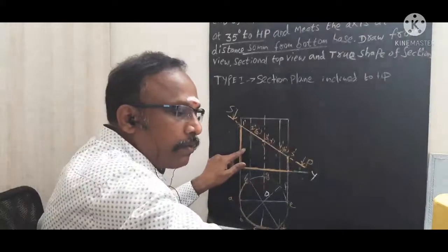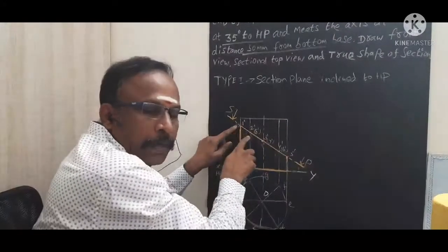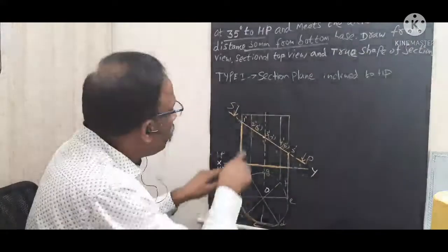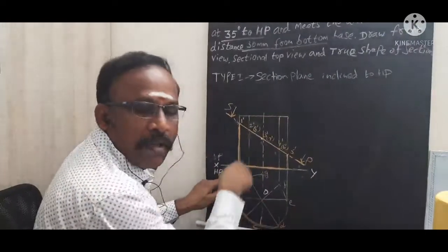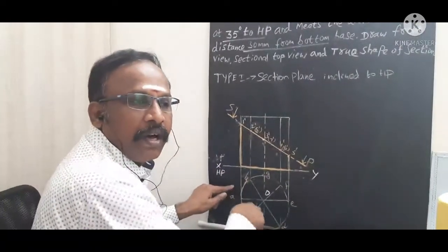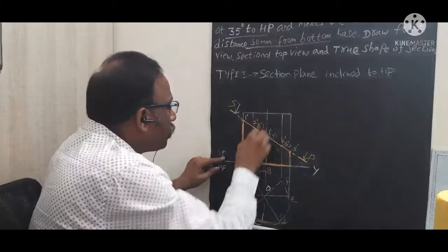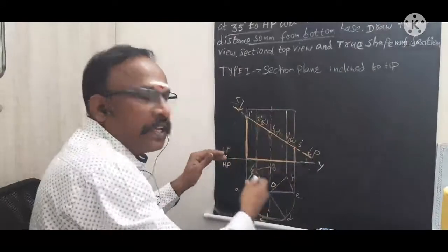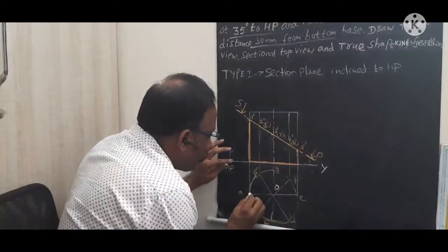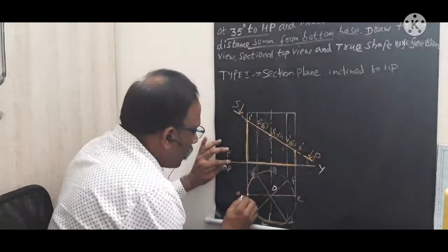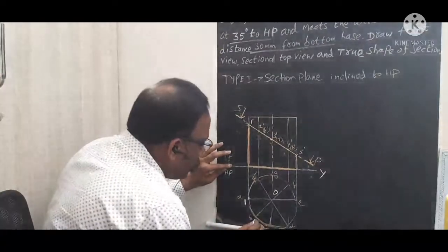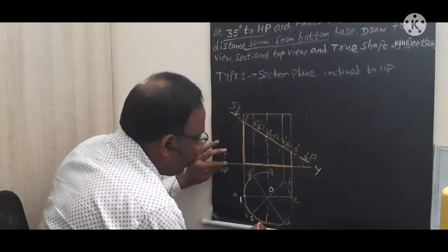Now, next step, we want to project these cutting points. These points we call cutting points. We need to draw the projection line from these cutting points to the bottom generator line, or bottom base. You need to project that way, because it cuts the generator lines exactly at this point. At the point A we mark 1, and B is the next cutting point name.